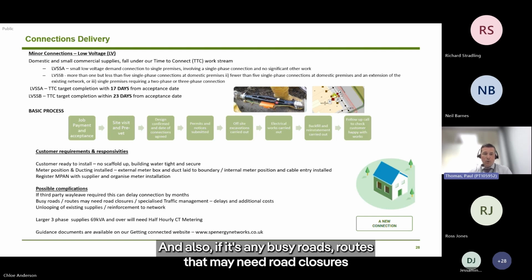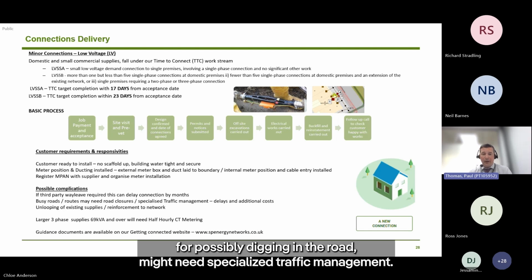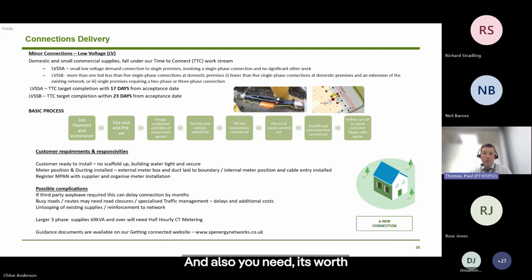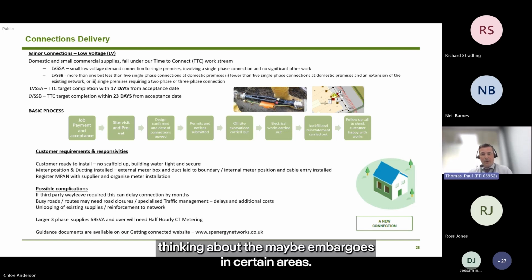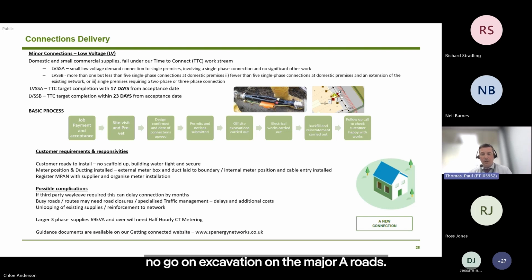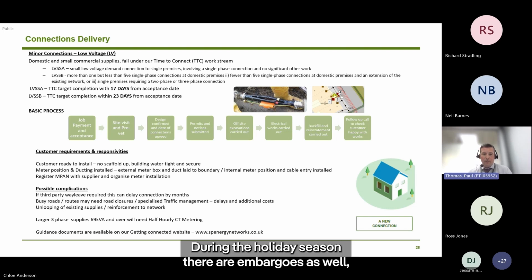Also, if it's any busy roads or routes that may need road closures, because we're going to be taking out the footpath or possibly digging in the road, it might need specialised traffic management. It's also worth taking into account that there may be embargoes in certain areas. So at Christmas in Liverpool centre, there's pretty much a no-go on excavation on the major A roads. Similarly in Wales in the summer, during the holiday season, there are embargoes as well.